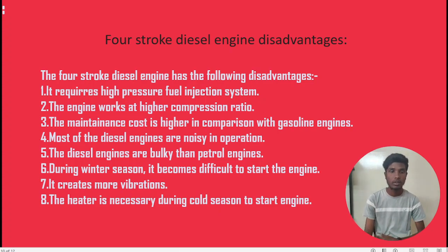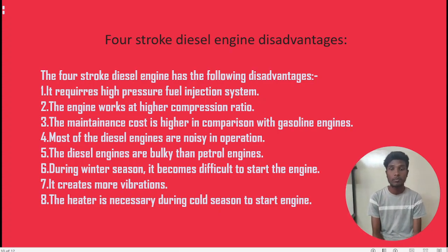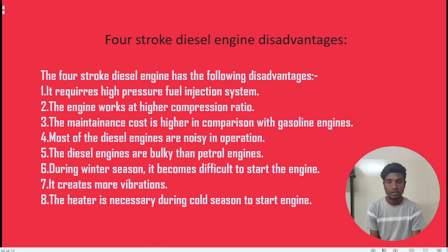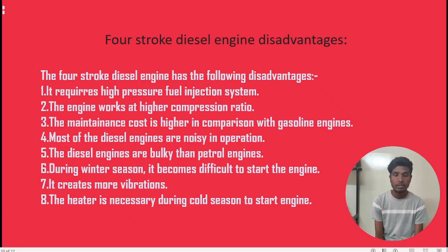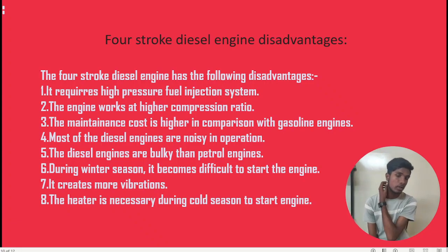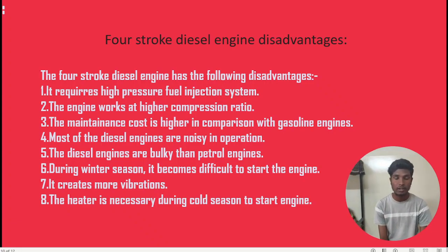And disadvantages: the four-stroke diesel engine has the following disadvantages. It creates more vibrations, and a heater is necessary during cold seasons to start the engine. In a cold climate we should start the engine with the heater, and during winter it becomes difficult to start the engine.